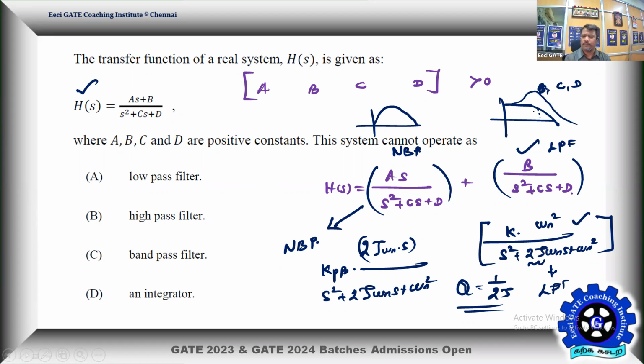We did not get into that deeper. So it is simply a low pass structure, and this is a narrow band pass structure. If you add the two, the result is going to have a frequency content ranging from 0 till the upper cutoff frequency of your band pass system. So this is going to have ω1, this is going to have ω2, and this is going to have ω_c. But values are not given. It's all about how you configure your given system.